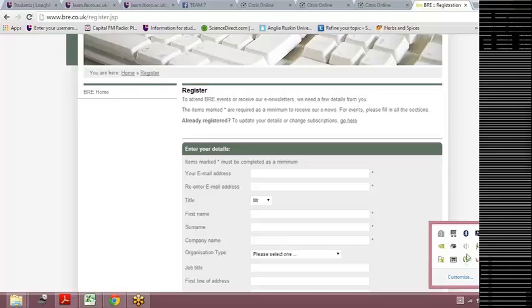So I've uploaded the calculations onto Dropbox. Basically, we've figured out what the loading will be, and we're extrapolating that for the rest of them. What we end up with is a minimum surface area, based on that soil, of about 1.1 meters squared as a pad foundation for each of the columns.